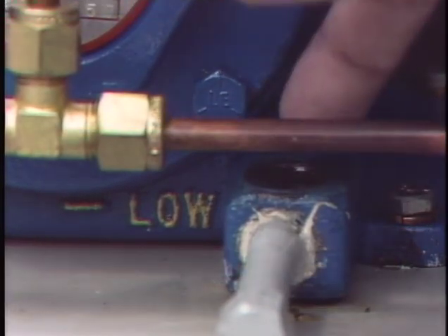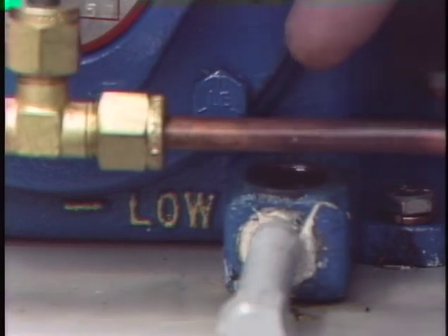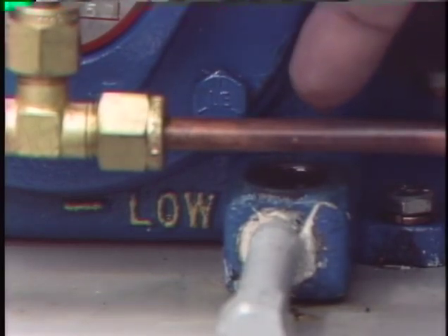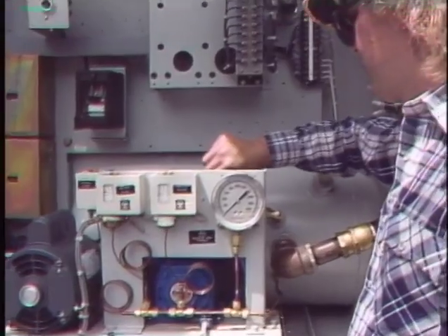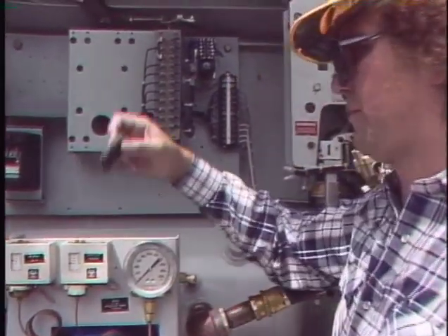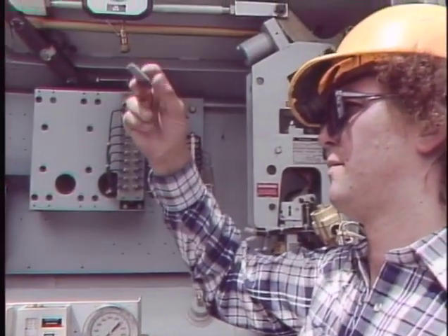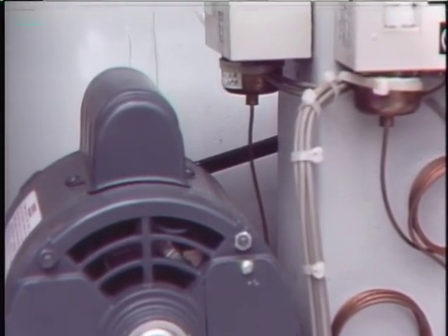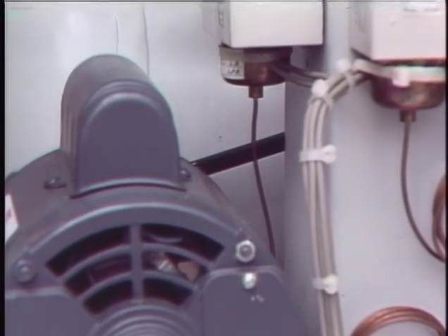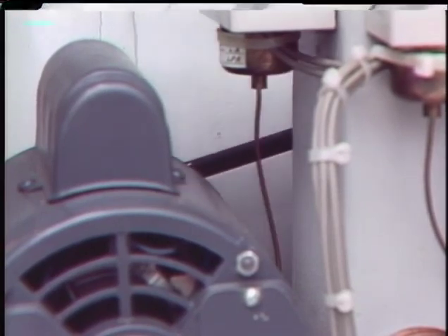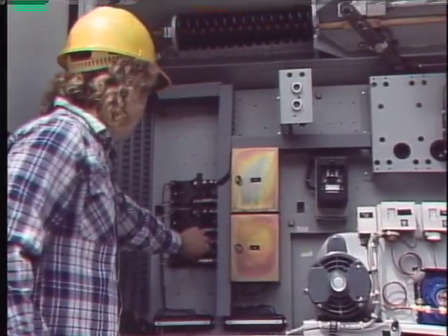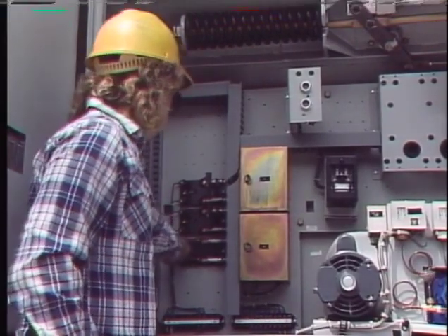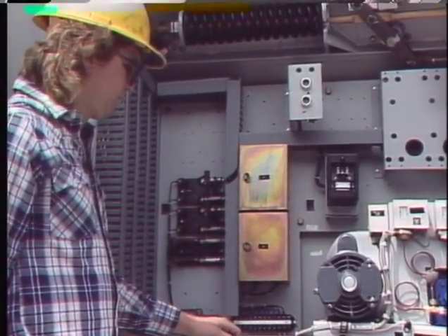The condition of the oil can also be easily checked. If the oil is dark or gummy, it should probably be replaced. The compressor air filter is inspected for dirt and is cleaned or replaced if necessary. If the compressor has a drive belt, it should be checked for signs of cracking or drying out and for proper tension. If the belt is in bad condition, it should be replaced. If the tension is off, it should be adjusted. After the compressor has been serviced, it can be energized so that it repressurizes the system.